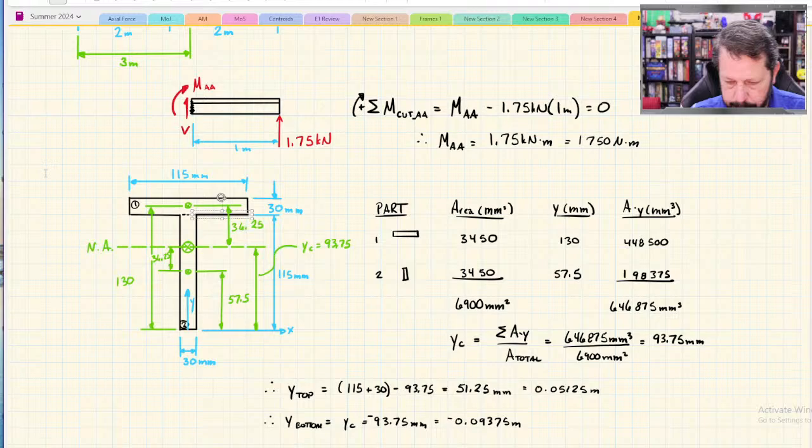So the mesh word that your question's about, the mesh is how many bricks are there in there. And you can control that in SolidWorks. The way I showed you to do it is kind of just take all the default settings. But on the left-hand side of the tree that you walk through, the history, there's one that's called mesh. If you right-click on that, I think you can either do properties or display mesh or mesh properties or something like that, and it'll just tell you how many elements there are. There'll be thousands, you know. Even at the default setting, there'll be 1,000 elements or something, or more than that even.